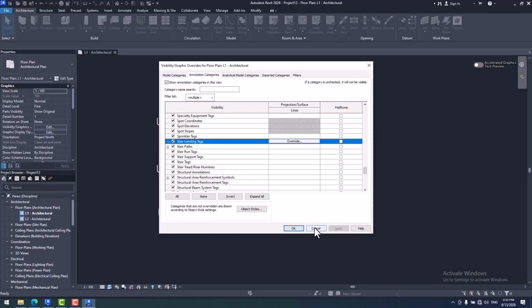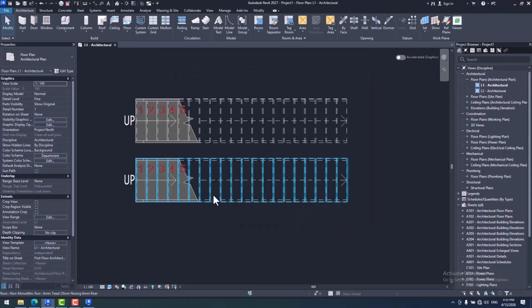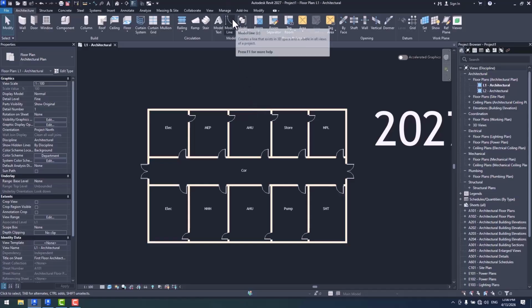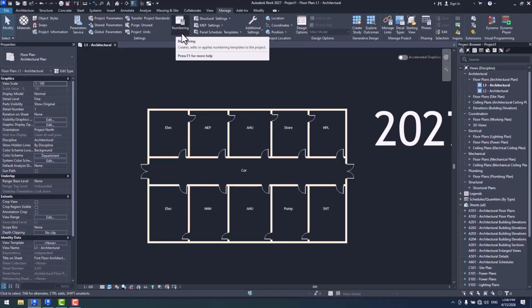Alright, guys, that would basically be all regarding the new features and points that we have for stairs in Revit 2027. As for another feature in Revit, actually a completely new feature, we can mention the numbering item. If you recall, back in prior versions, for specifying the numbers and even names for elements based on other items, like, for example, changing the name or even the type mark within doors based on the rooms, we had to use Dynamo. However, now we got this new, built-in item that we would be able to use for changing the name and numbers within elements based on other objects and items.